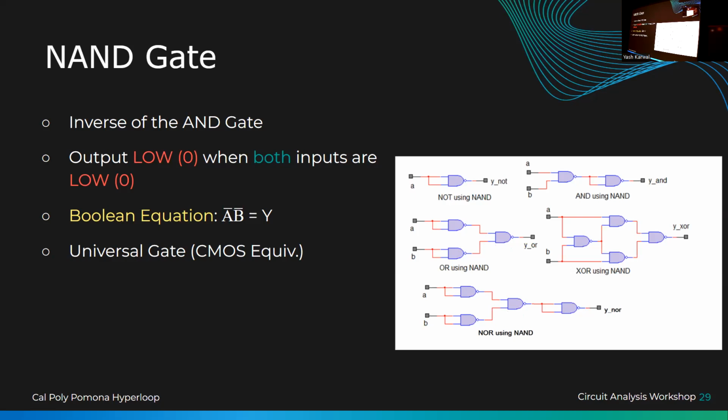It's easier to build an entire circuit out of NAND or NOR gates because you don't have to worry about all the different types. You can make any type of logic component with just NAND or NOR. A NAND gate is built out of transistors, so if you want to go even further back, that's where the logic comes from. And most SSDs use NAND and NOR for flash storage.